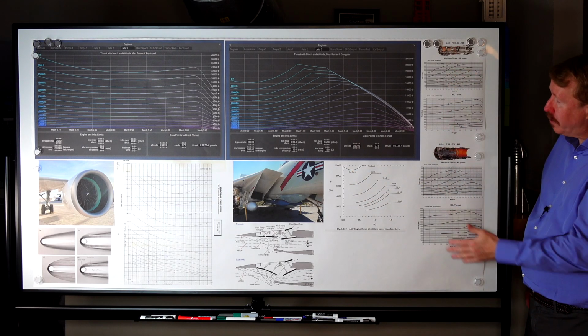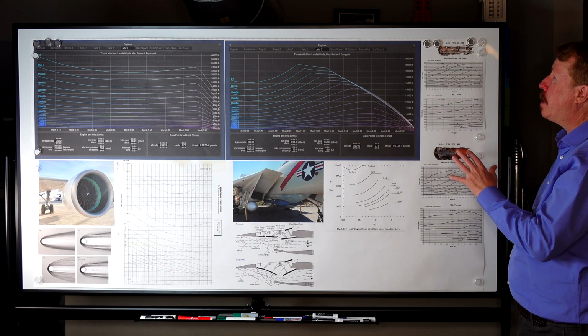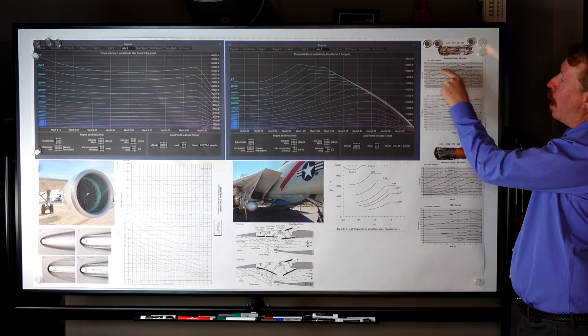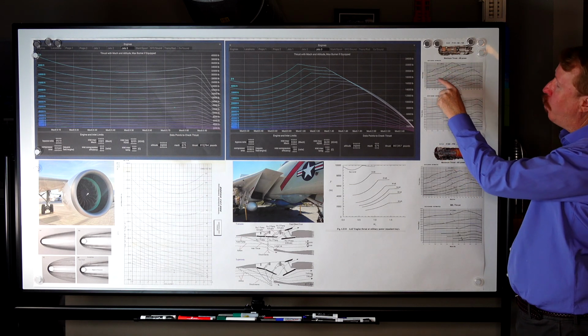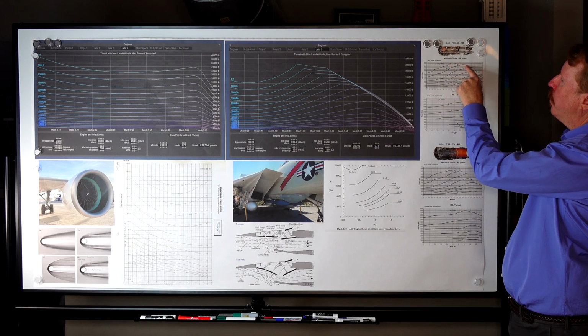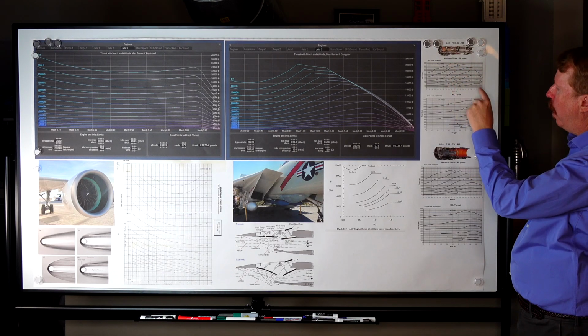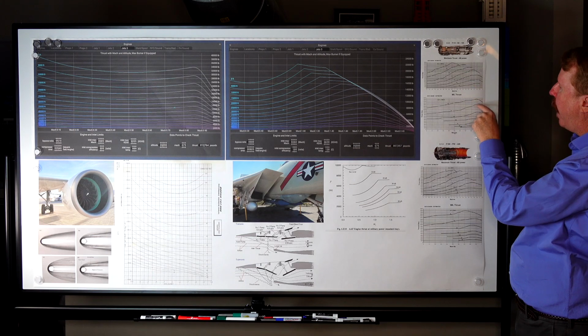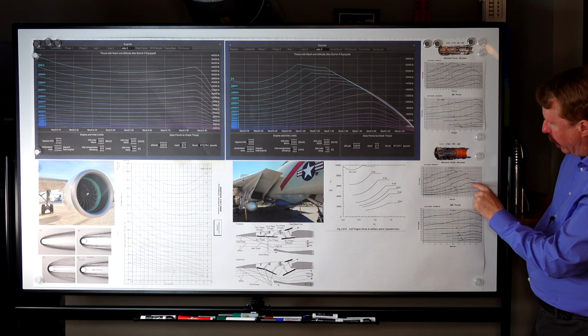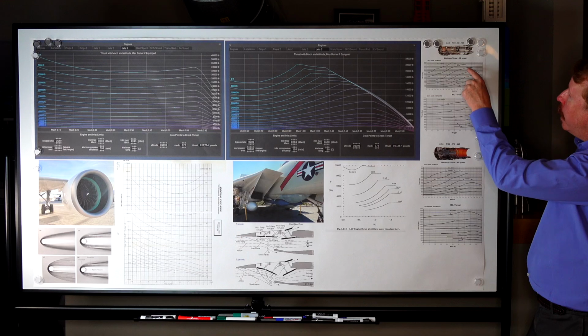And here's some more curves from some other jet engines, and you can see the same general trend. We build up as we get dynamic pressure and ram air effect build up. Then we hit some sort of a limit where we kind of flatten out, especially at low altitudes here. We flatten out a bit, and that is probably our indicated airspeed limit.